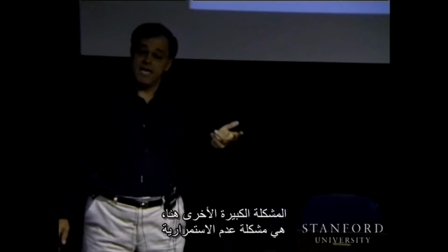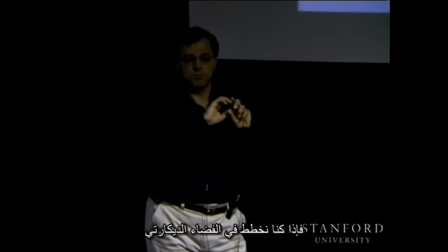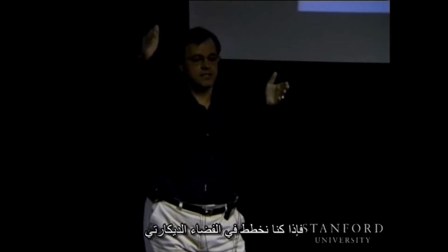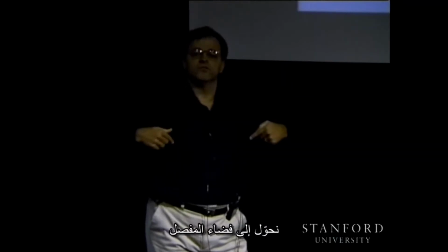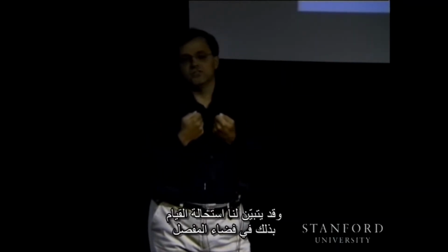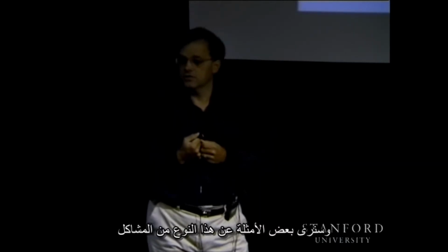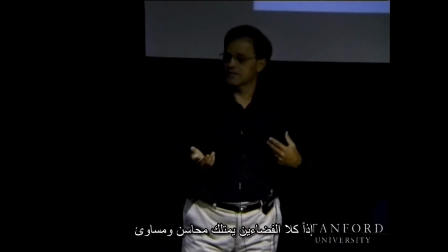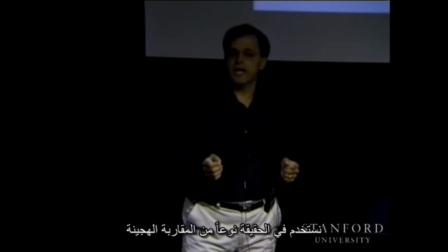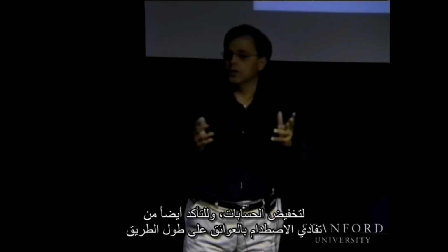And the other major problem is that we have discontinuity problems here. Because if we are planning in Cartesian space, we have our nice straight line that we are following in Cartesian space. We convert to joint space, it might turn out that it is impossible to do that in joint space. And we'll see some examples right now of this kind of problems. So both spaces have pluses and minuses. In reality, you usually use some sort of a hybrid approach to limit the computation, but also to make sure that you're not colliding with obstacles along the way.